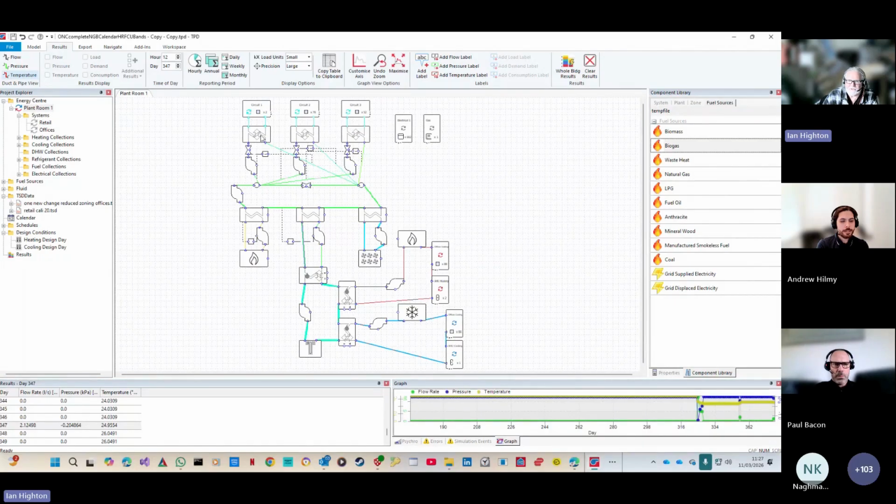So this is literally heat pumps going to indoor units and obviously supplying the heating and the cooling, and you'll see inside, I'm not sure you can see this, but 52, 78 and 2. So these are the number of retail units that are being serviced by these refrigerant circuits, and obviously the heat pump needs to get its heating or heat rejection from somewhere, and this green loop that you can see in the center is the retail primary loop.